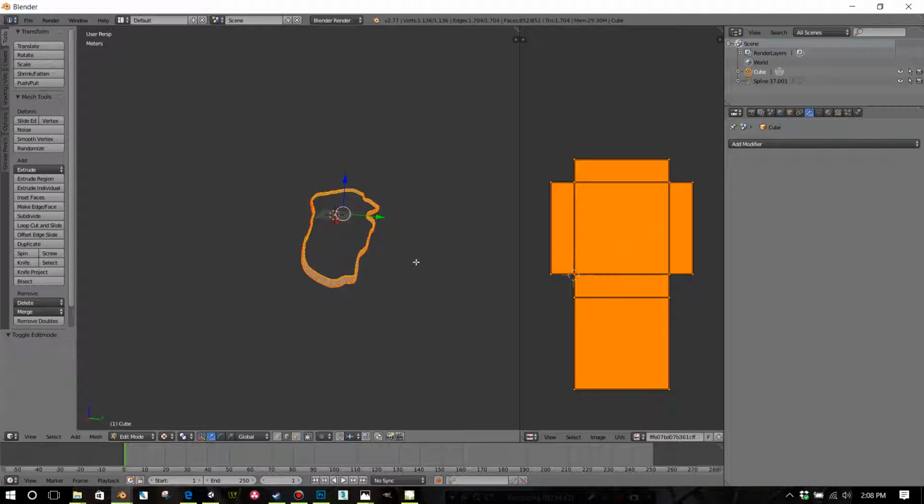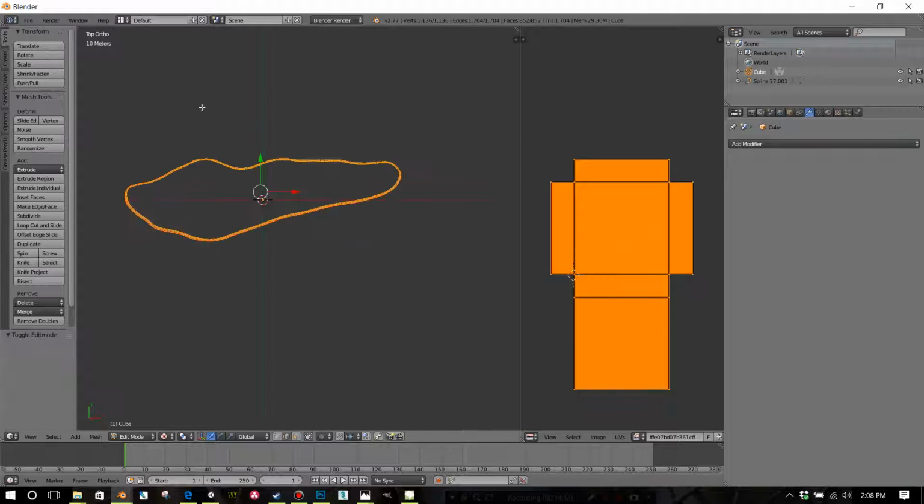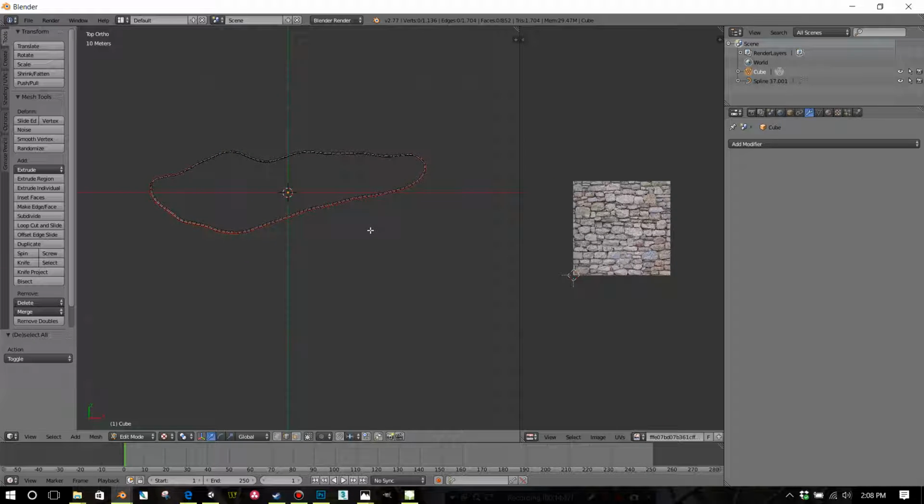So what I'm going to do is hit 5 and then 7. 5 put me in ortho mode. 7 put me in top. A to deselect it. And then I'm going to go ahead and see this here, this limit selection to visible.